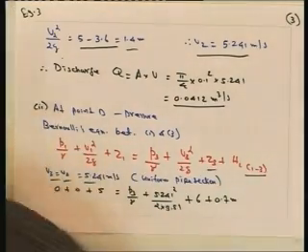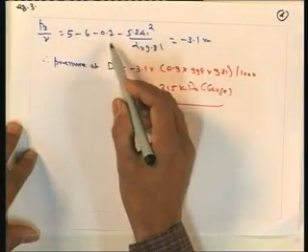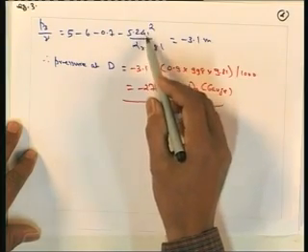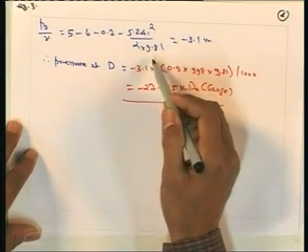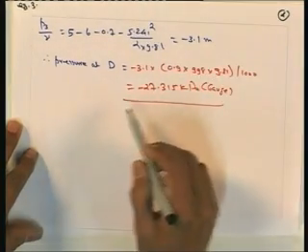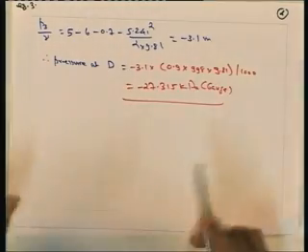Finally, we can get P3 by gamma as 6 minus 0.7 minus 5.241 square by 2 into 9.81. So, this is equal to minus 3.1 meter. So, the pressure at D, finally, P3 by gamma gives the pressure at D. That is equal to minus 27.315 kilopascal gauge. So, this is the pressure at D.